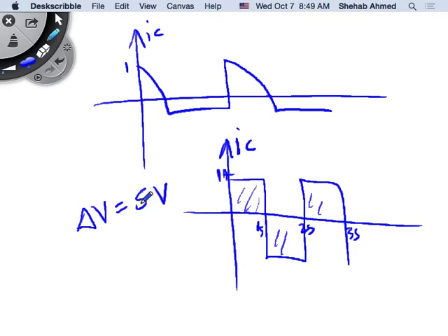If you're creating a low pass filter, you would like only the low frequencies to pass through, and all the high frequencies to be attenuated from the output. So what's happening? You are taking the low frequency energy to the output, and all the high frequency energy is being shorted out to the supply. So capacitors will maintain ripple voltage, inductors will maintain ripple current.